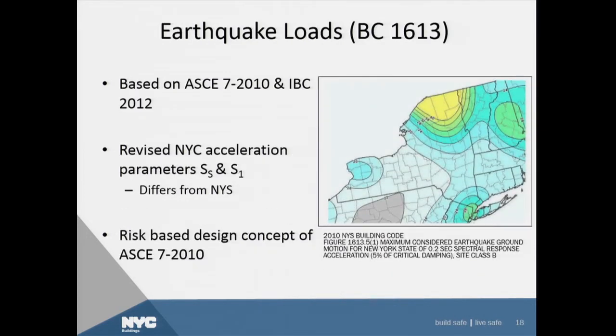Okay. Earthquake loads. Again, we've touched on this a little bit so far. For new construction, we're going to be based on ASCE 7-10, and the text of the 2012 IBC has been incorporated where appropriate into the 2014 Building Code. This is all in section 1613.